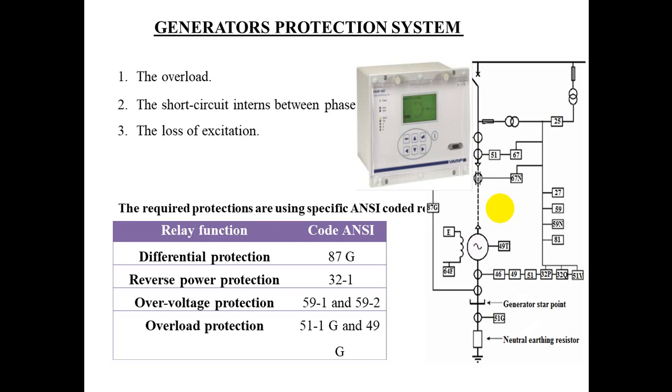The overheating is detected by embedded temperature detectors at various points in the stator winding. The temperature detector coils are normally resistance elements which form one arm of a Wheatstone bridge circuit.